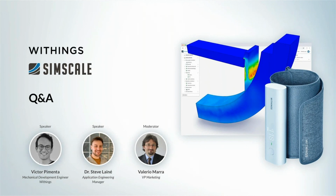Thank you, Victor. Thank you for the answer. Sorry, Valerio, if I can add slightly to that. One tip we have with the penalty coefficient for the person that asked is that it can be a bit of an iterative process. Once you've run a simulation with the range that Victor recommended, 5 to 50 times the Young modulus, you can check the post-processor to see if you've actually got some false penetration of the components. And if you do have that, you may need to increase the penalty coefficient slightly.